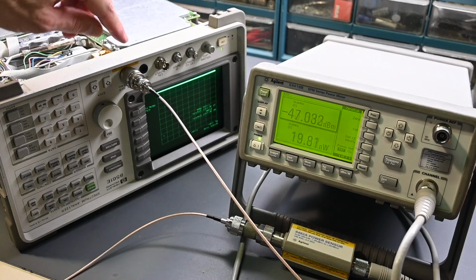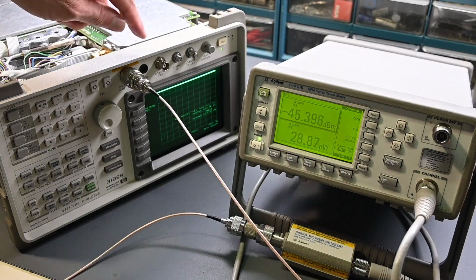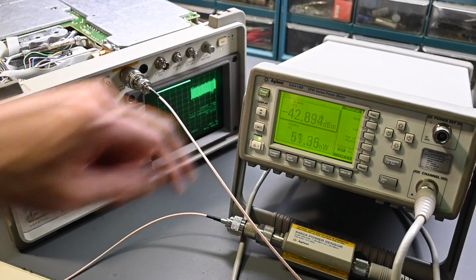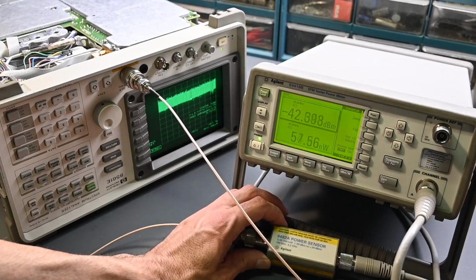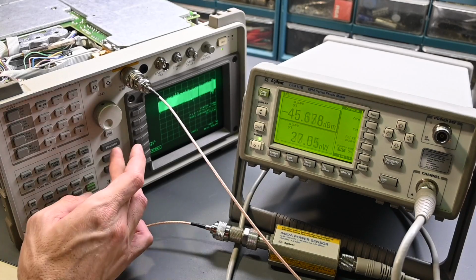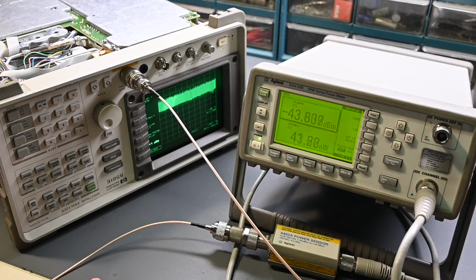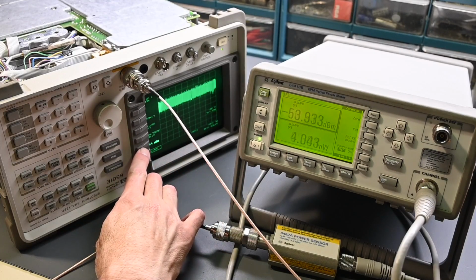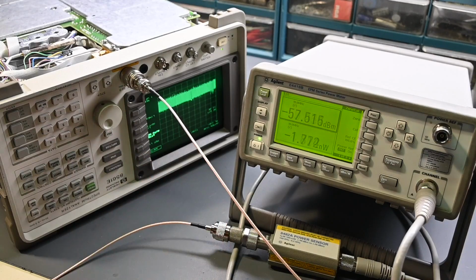By putting in exactly 0 dBm, when this steps through the 10 dB attenuation, then 20 and then 30 dB attenuation, we'll be able to easily see if those numbers match up over here. Now this power sensor only goes down to minus 30 dBm, so I can't go any further than that, but it'll give us a start. So it looks like it has started up here, and what I need to do is go to amplitude. Of course, it's upside down, so I've got to look at this kind of awkward angle here, but it looks like the attenuator is right there. We'll go over to manual mode, turn the RF output on.